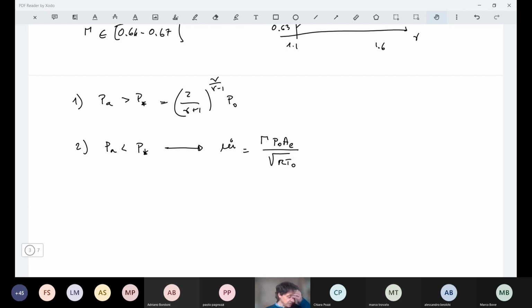So an interesting point here is that we have realized the choking conditions. So we know that reducing this pressure, we have this choking condition. Then we can say, okay, we have reached the maximum flow rate and also velocity is good, and we stop here.